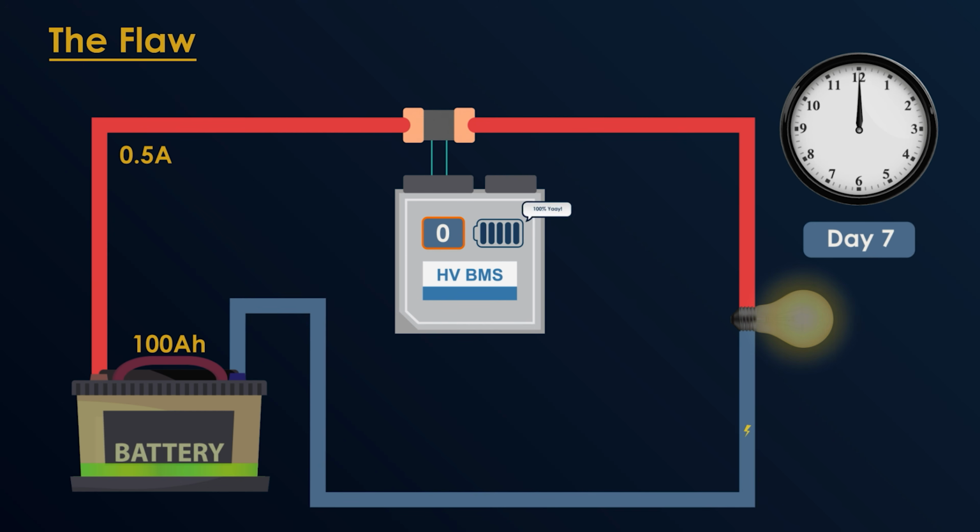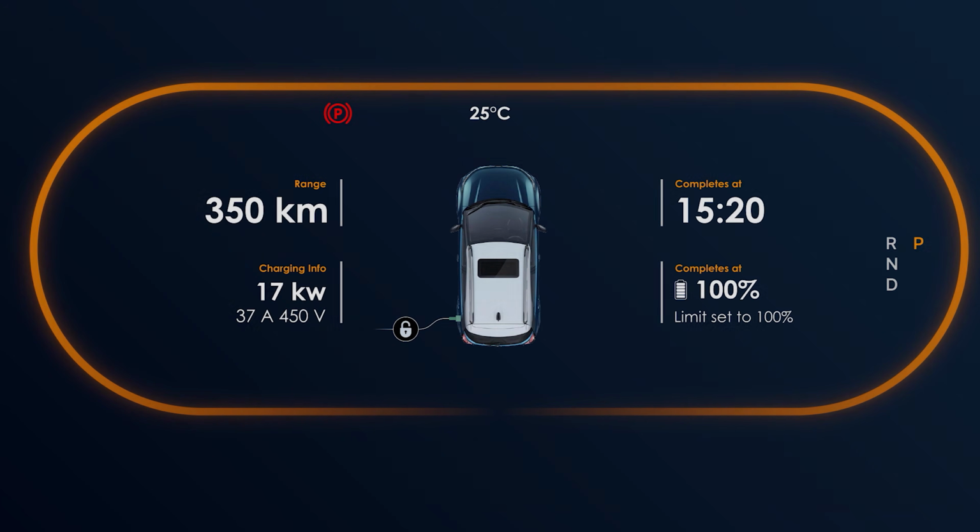Yay! Then suddenly, poof! The voltage hits the cliff edge. Our BMS triggers a low voltage disconnect to save the cells from permanent discharge. And our lights go out. We're left in the car screaming at an app that still says 100%. We call this SOC drift, and it is the reason we hate such EV BMSs.